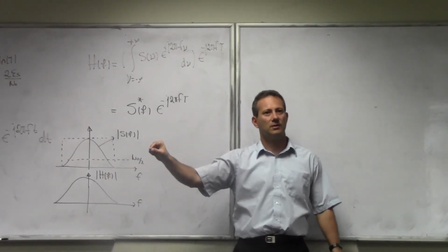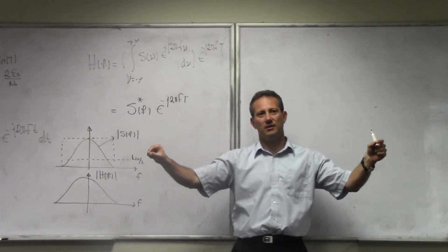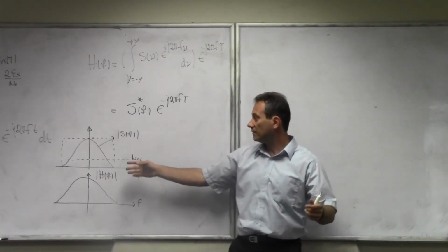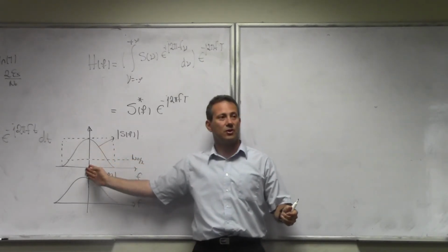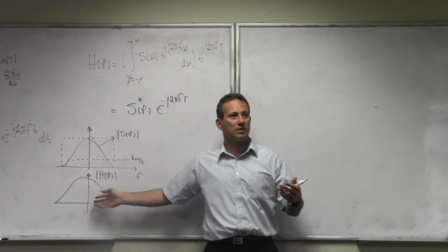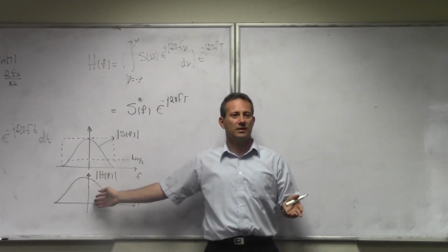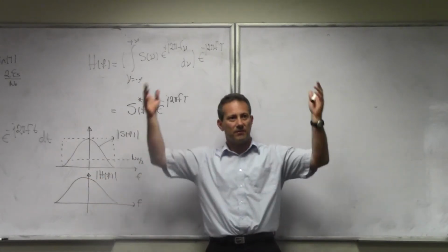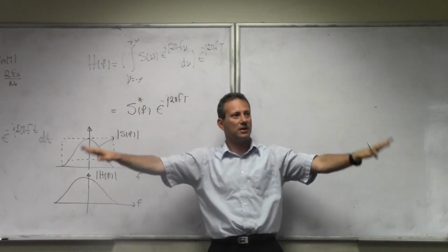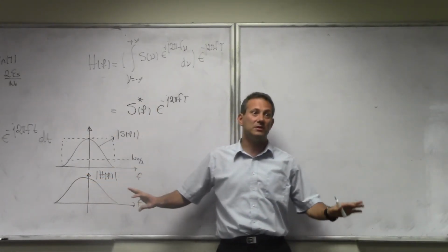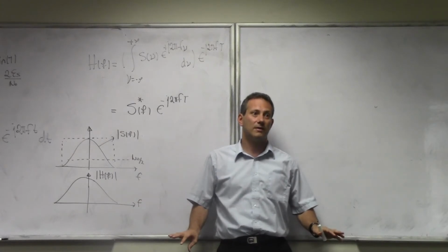What comes out is different from what came in. The signal gets distorted, right? Why? Because the fine relationship between sinusoids that built this signal in the first place is now disturbed by the very filter that I'm using to demodulate, right? Because I'm taking the components, for example, that are here, and I'm amplifying them, and taking the other components and attenuating them. So what came out of the matched filter is going to be different than the signal itself.